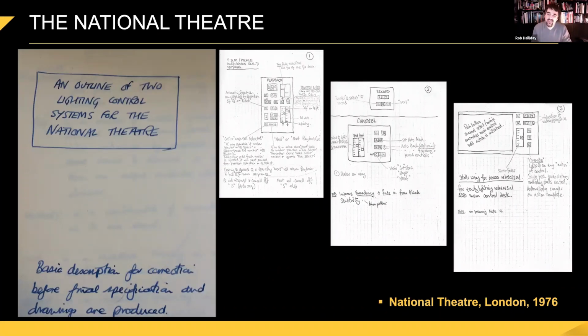It was about the lighting designer being able to interact with the lights if they wanted to, rather than having to dictate commands to an operator. And it was about having integrated control of the moving lights, and also the color changes the theatre had, which was semaphore fold in, fold out color changes, and also slide changes on their projectors. And also, just for this massive rig, the Olivier had 800 dimmers at a time when the average was probably 100 to 150 dimmers in a big theatre. 800 dimmers to cope with this big permanent rep rig.